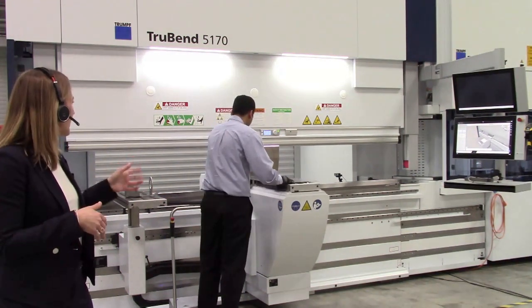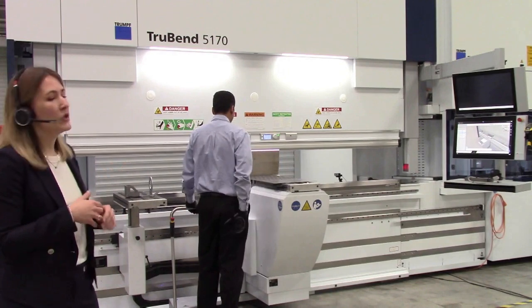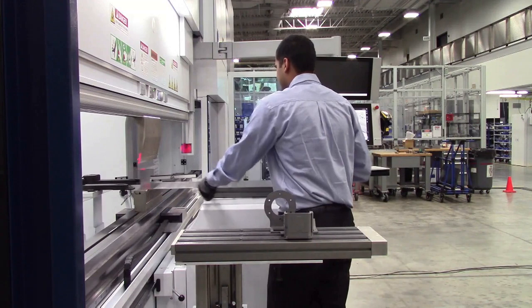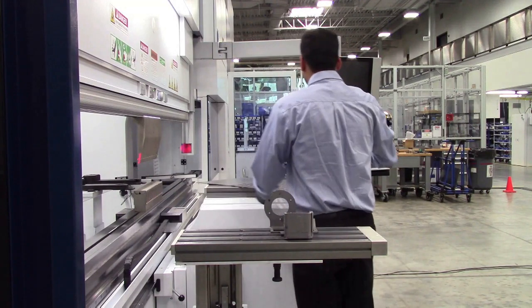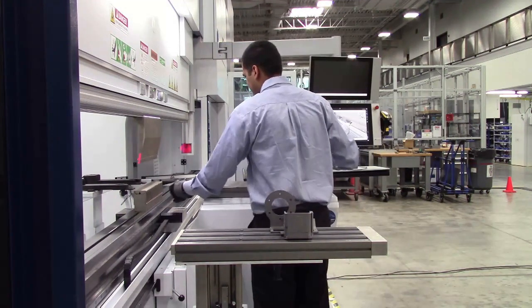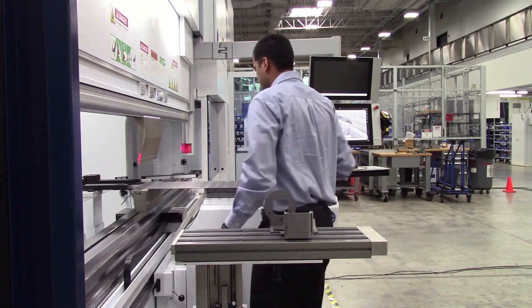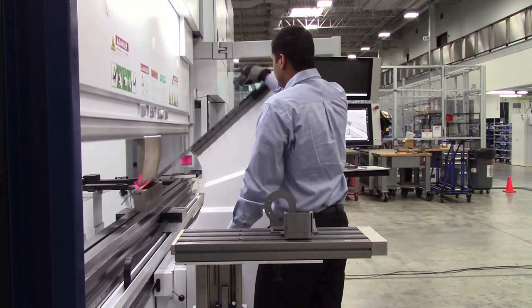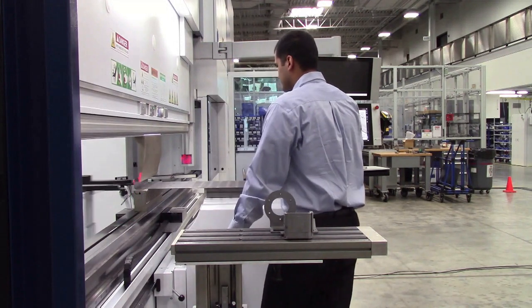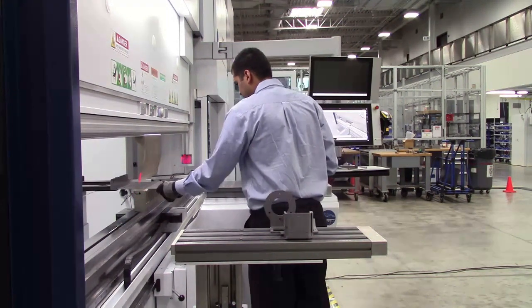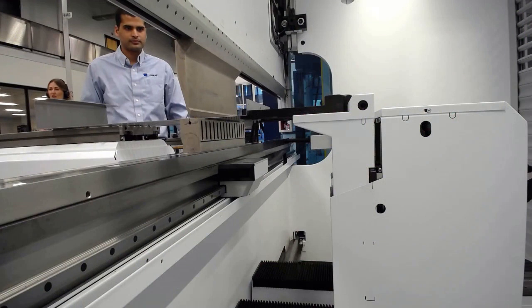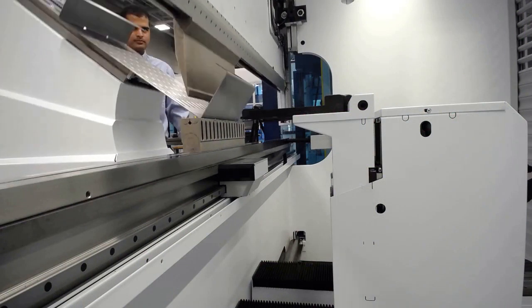During this part, Anurag is using the learn function of ACB Laser. While in the first part that we bend, ACB Laser measured every single time, we're now measuring the first time, and whatever the machine learns from that spring back and that correction that it makes, it will apply to the rest of the part as well. So we only need that 1 extra second for the first bend, and then the subsequent bends will be even faster.